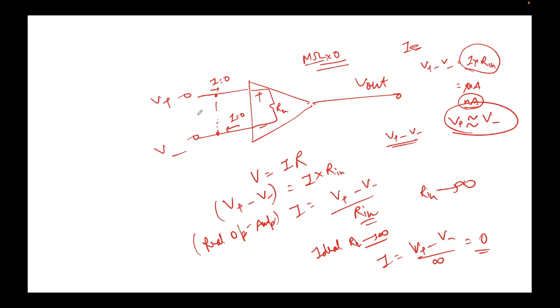That's a different case. But for solving those problems, let's say you have some negative feedback here, RF and some resistor R1 here, then you can assume that whatever voltage is here, due to the virtual short, that voltage is being reflected here. This is due to Ohm's law across this resistor. That's what I meant by virtual short. Is it clear now? Yes. Okay, good.